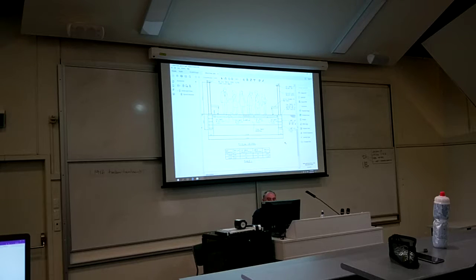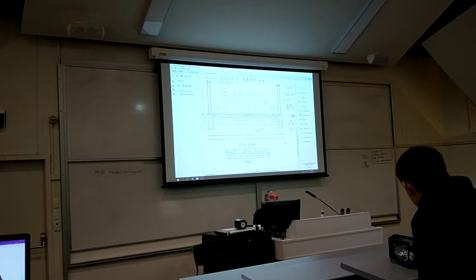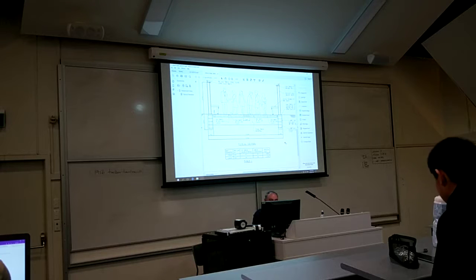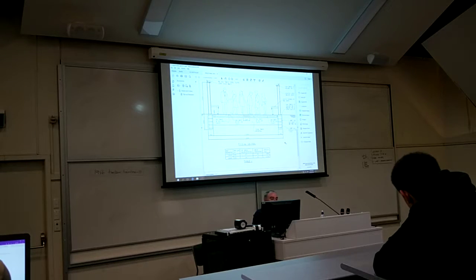So I get students that go, well, hold on, I've just been online, and the minimum length bar that you can buy is 9 metres. If you lap that in the middle, you're going to lose a lot of money by the time you finish doing the job. That's correct, but that's taking it a little bit too far. In the real world, they tend to look at what bars are available, and they make it work. I did a job in Indonesia, way up in the mountains, and we did a perfect design, and then they said, oh, the helicopter's just dropped off all the reinforcing, it's the wrong size. So we had to redesign it for the size of bars that were there and use those. That's fine. But in this job, working for me, doing this assignment, please assume that the lap is in the middle and there isn't any minimum size bar that we're ordering for this job.